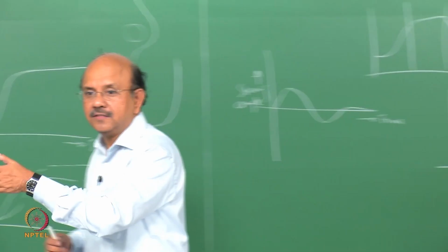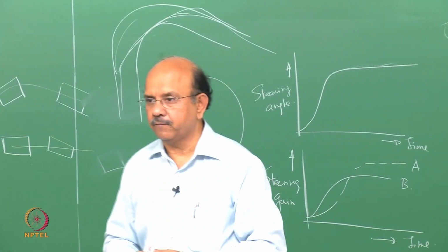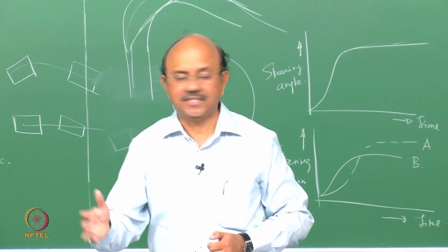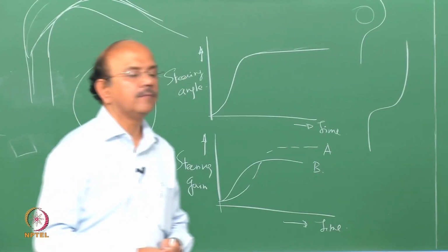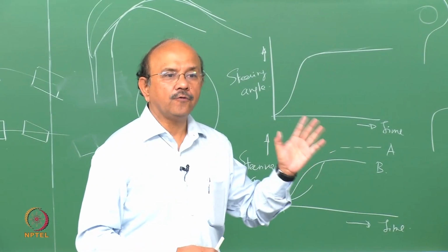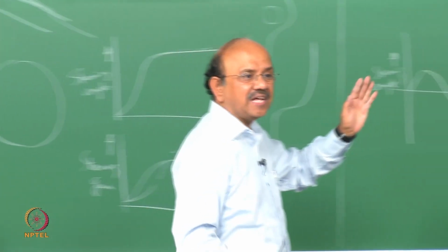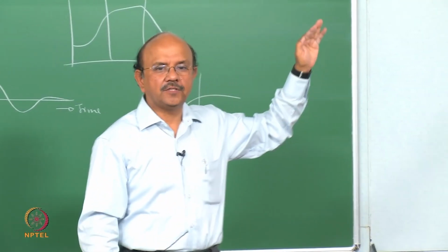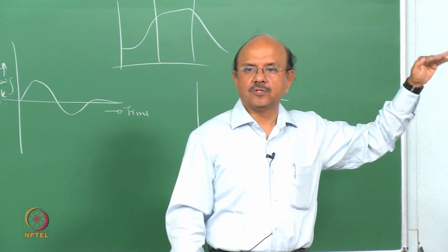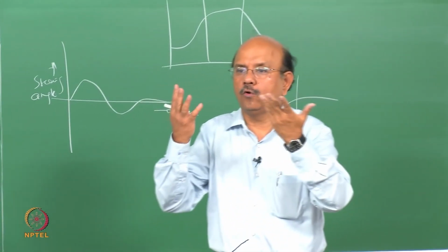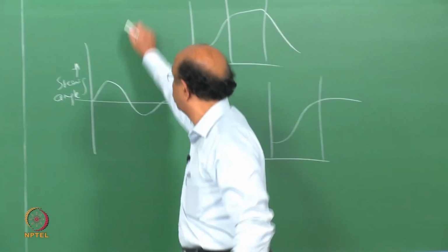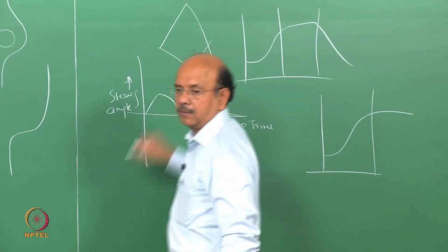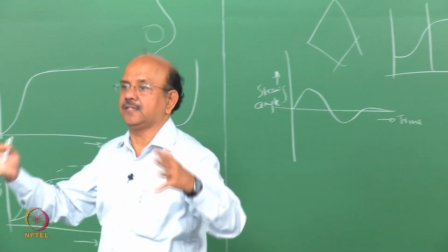The phase of the road wheel steer at 0.4 Hertz. Yaw at 0.4 Hertz. So these are the further metrics that were added as far as the frequency response is concerned. So they expanded the metrics. No more just four that form a rhombus. So the numbers are increasing.